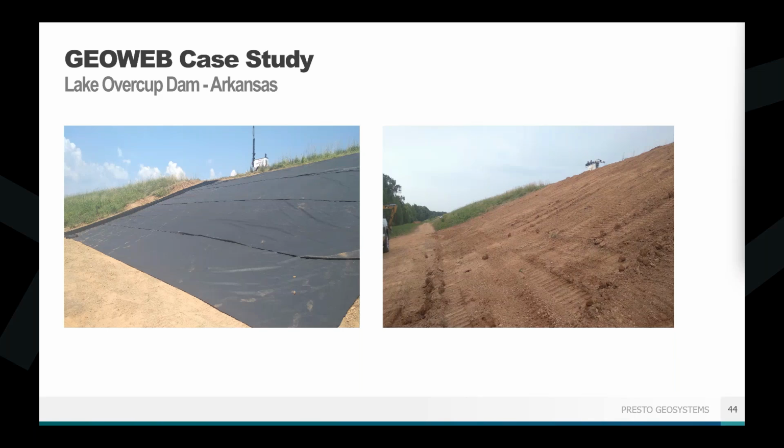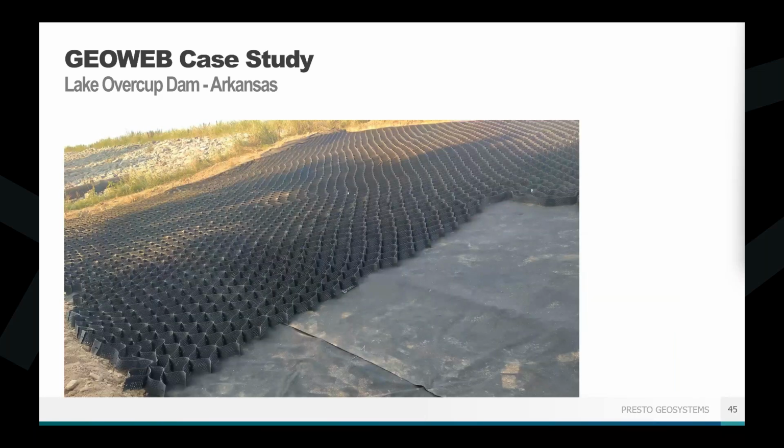In this case, they chose the 4-inch deep GEOWEB panel, and they filled those in with topsoil. And here the panels were anchored with the ATRA speed stakes. Those were the 100% HDPE stake, that molded plastic stake. This is a really great choice in this particular case because they aren't going to corrode or degrade in the environment. So if they get wet, or if they're around corrosive soils or anything like that, nothing is going to happen to those HDPE stakes. They're going to stay strong and stable the entire time. They were easily able to put those in. Again, this is only a 3-to-1 slope face, so pretty easy to work on. Filled that all in with topsoil.